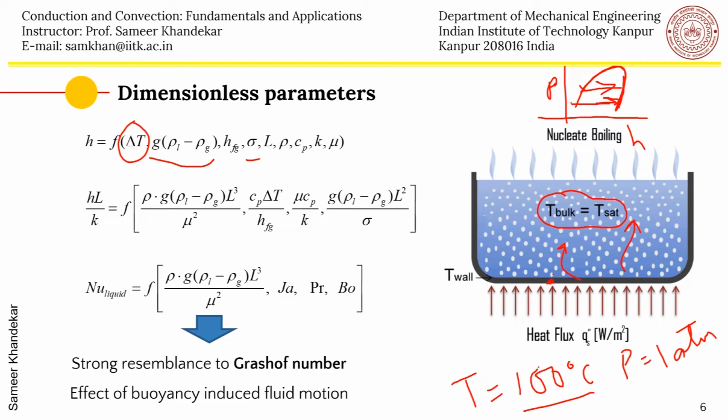There is a typical length scale. The length scale can be the size of the bubble, for example. The densities of liquid and vapor play a role. The specific heat of the liquid plays a role. The thermal conductivity of the liquid plays a role, and the viscosity of the liquid, because the bubble has to now travel upwards. It has to first grow. It has to push the liquid away and then grow and then leave the surface and then travel upwards. So there is friction, which is in the form of the viscosity of the liquid and the vapor.